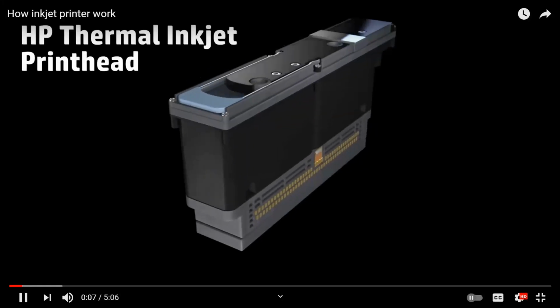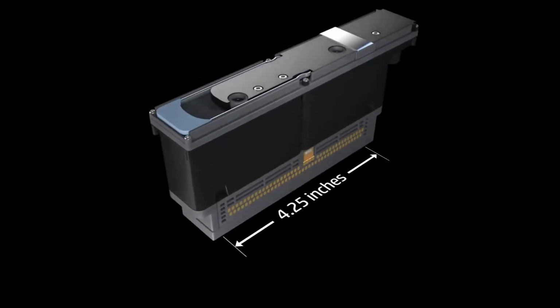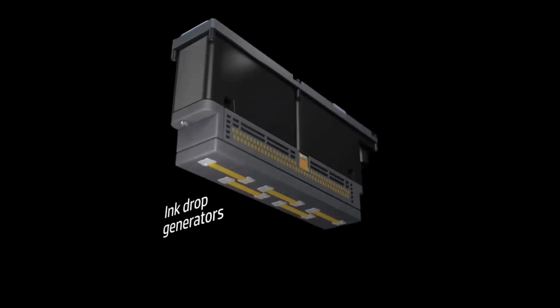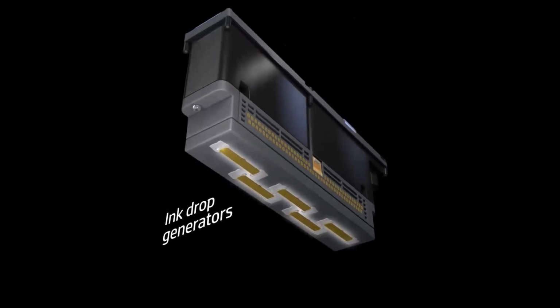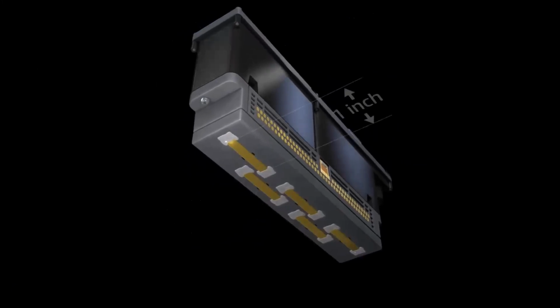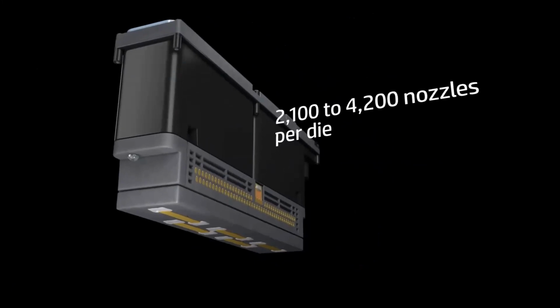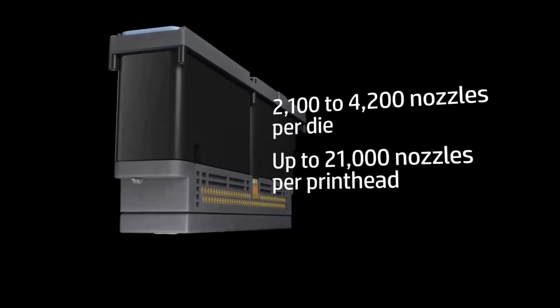This is an HP thermal inkjet printhead. It prints a swath 4¼ inches or 108 millimeters wide. The ink drop generators are on 5 staggered silicon chips called die placed along the bottom. Each die is about an inch long and can have 2100 and even 4200 nozzles. So some versions of this printhead have 21,000 nozzles.